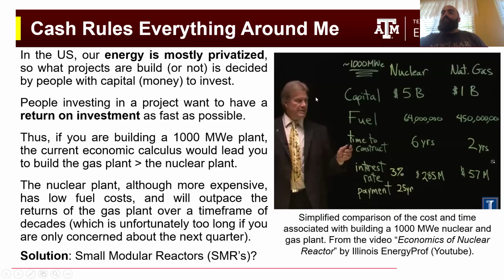So, imagine this isn't the business guy, this is Illinois energy prof, but imagine this is the business guy, and he's looking at building a nuclear plant or he's looking at building a natural gas plant, and he's deciding, I need a 1,000 megawatt electric plant. The nuclear plant is going to have much higher upfront capital costs than the natural gas plant. So right off the beginning, I would have to finance $5 billion to build the nuclear plant versus $1 billion to build the gas plant.